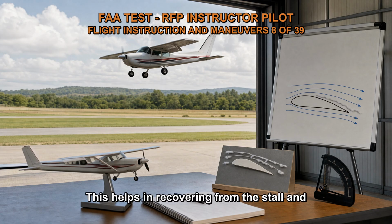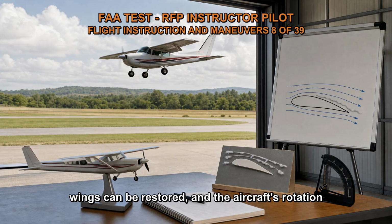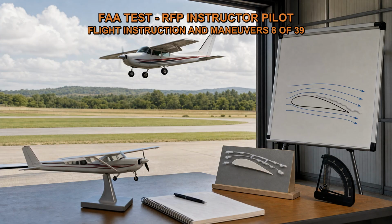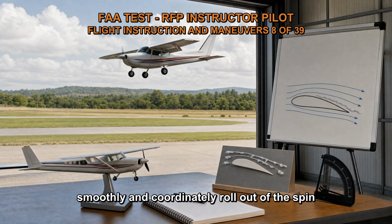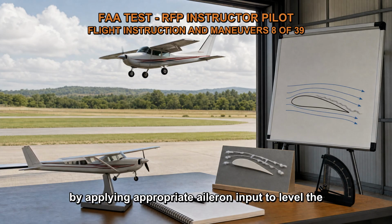This helps in recovering from the stall and allows the wings to regain lift. By following these steps, the airflow over the wings can be restored, and the aircraft's rotation can be stopped. Once the rotation stops, the pilot can then smoothly and coordinately roll out of the spin by applying appropriate aileron input to level the wings.